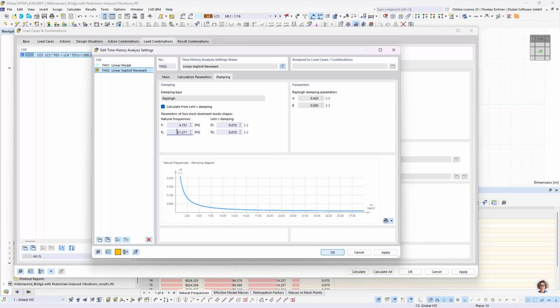And one hint for at least non-linear time history convergence: if you had contact with that analysis already and you didn't get your analysis to converge, just try setting this beta value to 0. Because with that, I don't know what is in the model, right? So if there's a really, really stiff object in the model that could be on some value of 30 in this diagram, then that would result in extreme convergence problems. So with setting this to 0, you wouldn't have the problem of an infinite damping for whatever frequency. I mean, except if you're in the first range, but that's another topic.